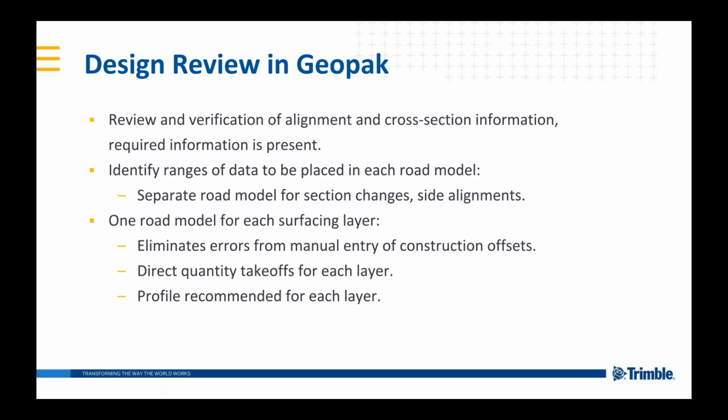For example, top of dirt, top of different base layers, sub-base, crush base layers, rather than doing construction offsets or dial downs to come down from a finish grade. We find that this really eliminates the errors from any kind of manual entries, any fat fingering, whatnot. It also allows you to do direct quantity takeoffs right from that road model for each layer. And then we also, if possible, generate a new profile for each layer as well. So profile for top of dirt, profile for the different base layers, so that we've got a clean surface to work from.